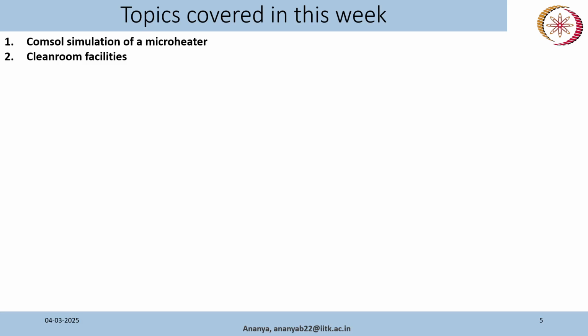Also, the lithography room was shown there. You have noticed that there was yellow light in the litho room, that is to prevent some unwanted exposure of the photoresist. So as we discussed, the photoresists are sensitive to UV light. But photoresist is also sensitive to a few wavelengths of blue light as well.